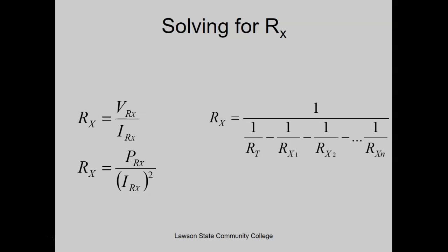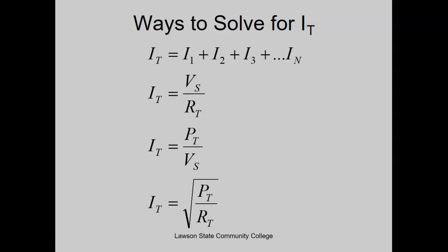Well, I'll put it to you this way. The reason you want to know some of this is because if you're, let's say, an electrician, you kind of need to know what loads you're going to be wiring in. Because if you wire in the wrong loads, you lower the resistance too much, and you're going to exceed the current so much that you end up burning something out. Master electricians have to know what they're doing. And this is part of what they have to know. Because if they don't, they ain't just risking their lives, they're risking the lives of a lot of people.